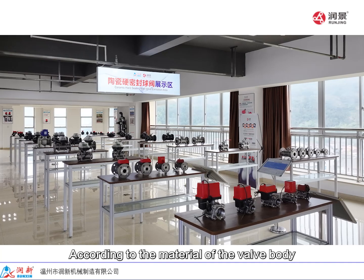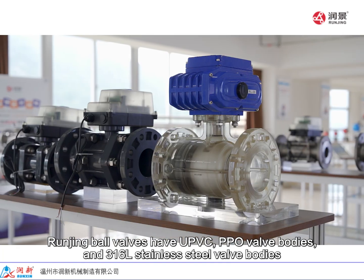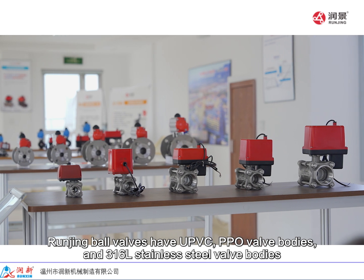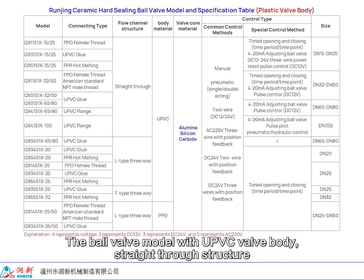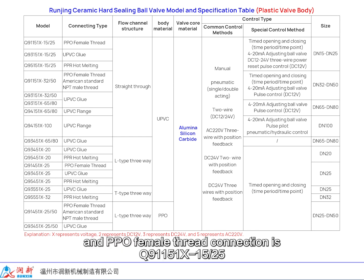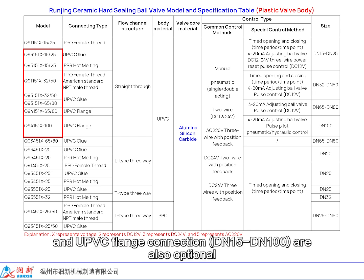According to the material of the valve body, Runjing ball valves have UPVC, PPO valve bodies, and 316L stainless steel valve bodies. The ball valve model with UPVC valve body, straight-through structure, and PPO female thread connection is Q91151X15 or 25. UPVC glue, PPR hot melt, American Standard NPT female thread, and UPVC flange connection are also optional.